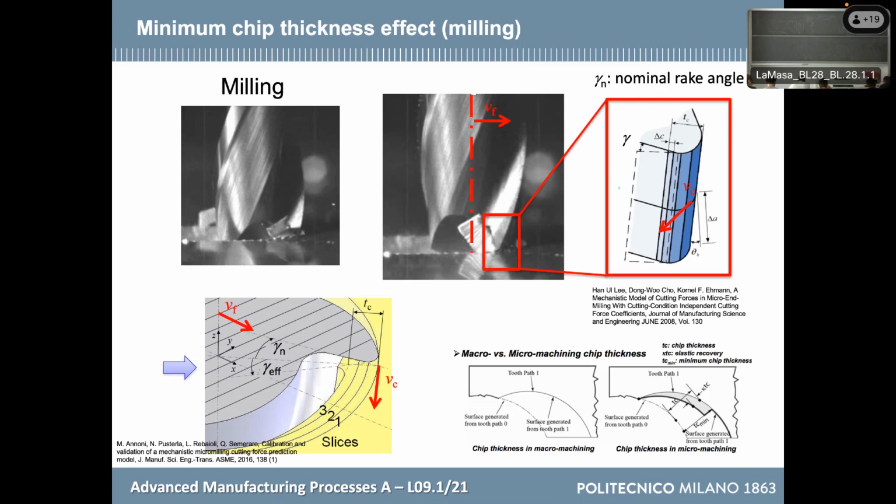So for this reason, when you see a milled surface, if you look better at the sides, for example, if you look at a slot milling operation, in the middle, you probably will see good striations, because a good milling operation must leave striations. It cannot be perfectly flat. But at the boundaries, a blurred surface, because the chip thickness in any case will be so small that the mill is smashing the material.